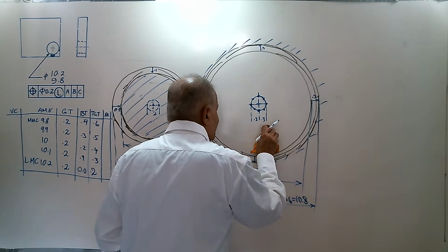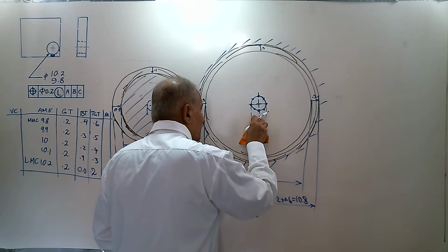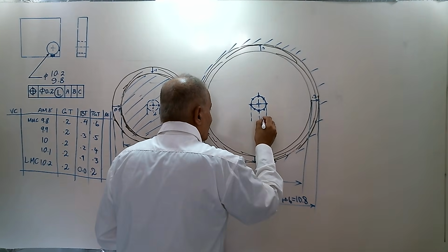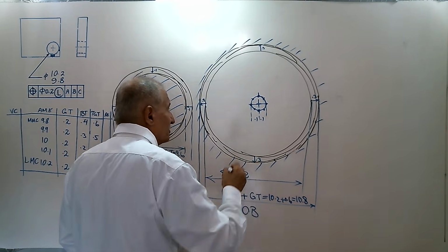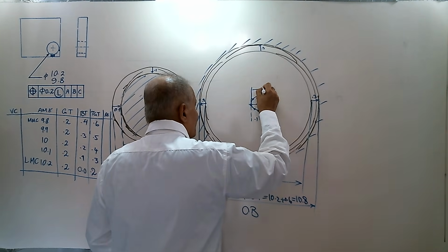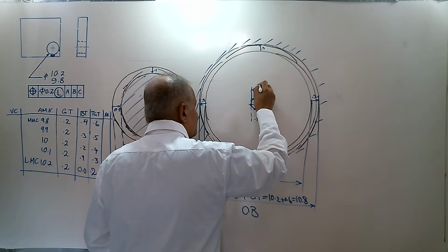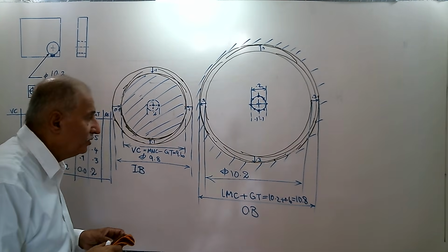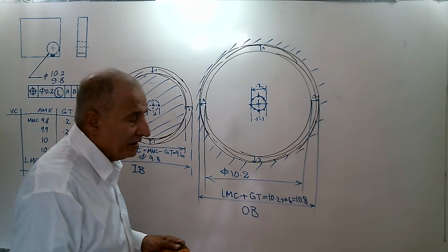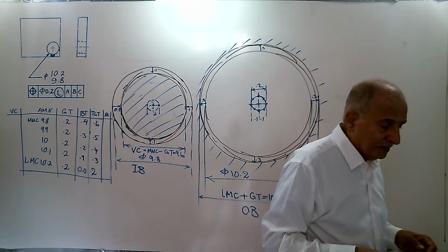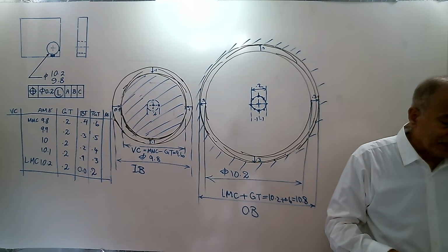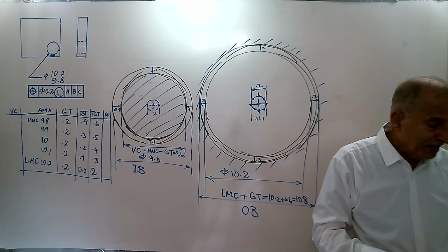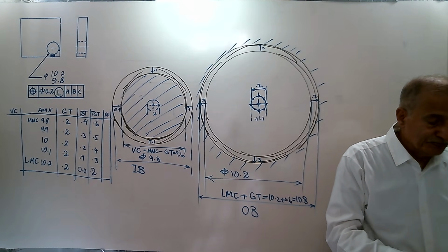If you consider LMC, this should be 0.1 and 0.1 here, because the total geometric tolerance for position at LMC that you produce at 10.2 is 0.2. It says that at L modifier, at LMC,